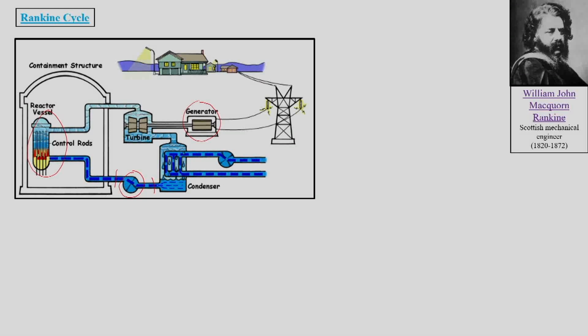In some format it may be saturated or supersaturated. Then this vapor goes onto a turbine, a high pressure and high temperature vapor going over the turbine and rotating it while getting expanded. In the process of expansion, the steam loses its enthalpy, its energy content, and comes down to the low pressure, and hence to low enthalpy,